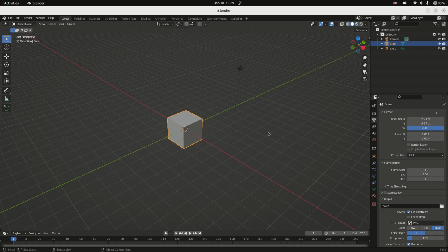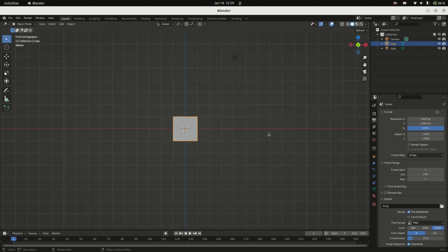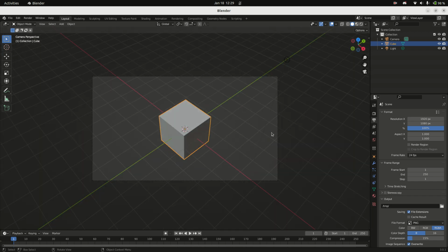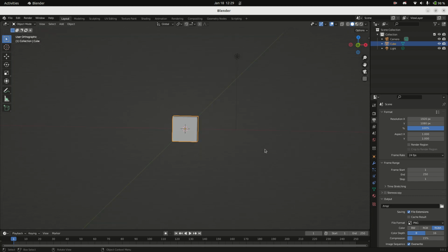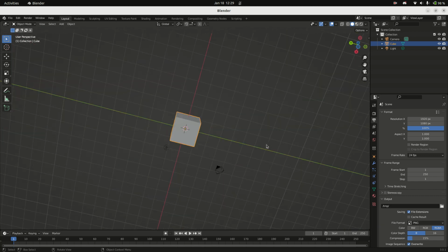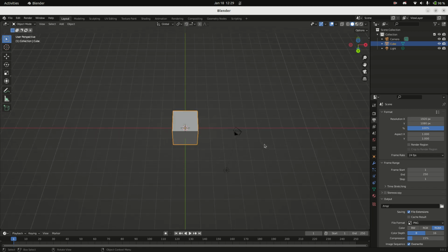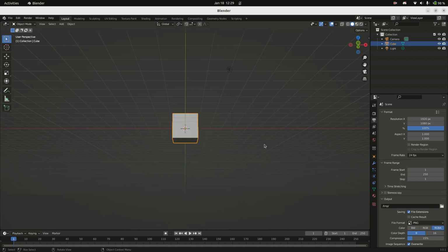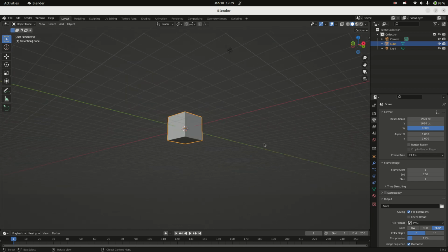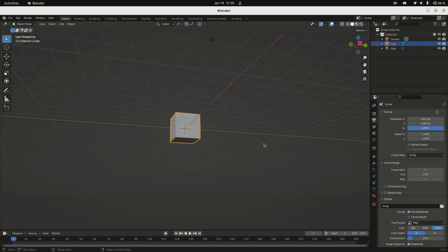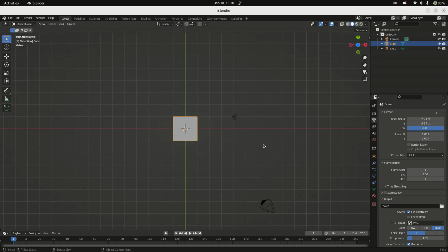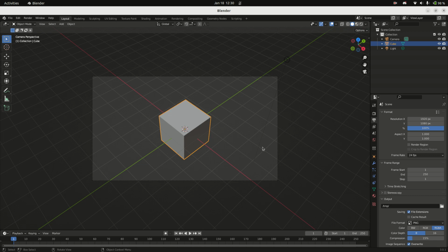All right. Now that you know these hotkeys to go between the different views, 2 and 4, if I'm in, will rotate out, and 6, 8. So 2 and 8 are opposite on the number pad. They rotate vertically. And 4 and 6 are opposite on the number pad. They rotate horizontally. And then 1, 3, 7, and the fun one, what the camera's looking at. Now I find these to be so useful. I oftentimes want them to be my primary view setup. I want to see all 4 of them at the same time.